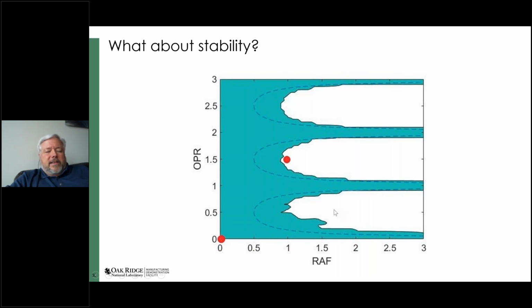And so in fact, this strategy, which we were using to break the chips, also turns out to be useful for chatter suppression. And I don't really have to get very far into the chip breaking zone in order to make that happen. So that turns out to be a good thing.